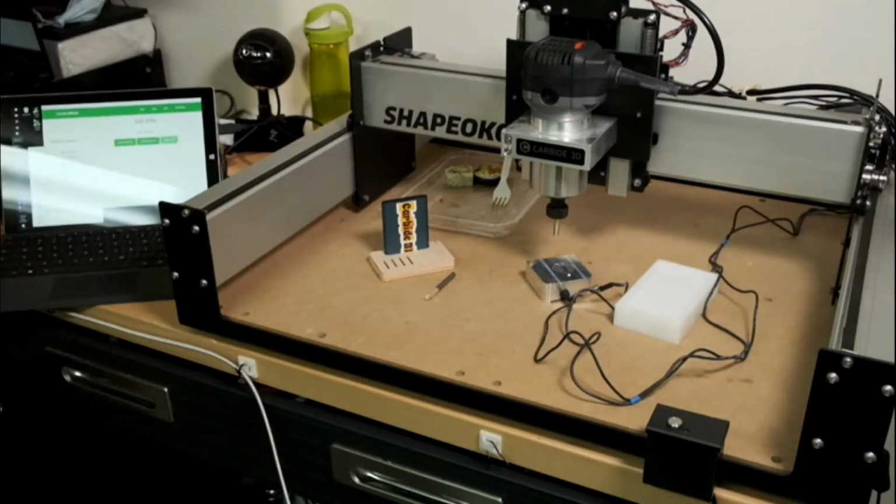Let's see what's next on the agenda. How do I check to make sure BitSetter will work? Do I have M6 in my G-code? Well, we actually just did that check previously for the Nomad.